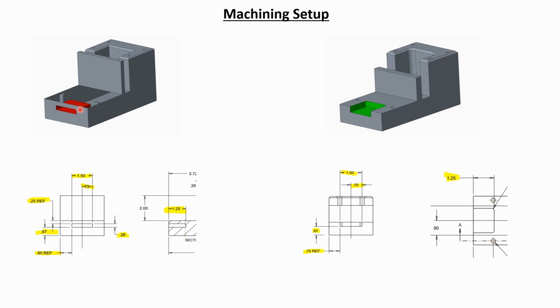The cutting tool approaches the workpiece at a 90-degree orientation. The original part will have to undergo a second setup to achieve that orientation. The corners of the internal features would also need to be rounded in order to use an end mill to achieve those features. If we look at the redesign, if the feature is redesigned as shown, then the entire part can be achieved within one setup, and unnecessary complexities which lead to more expenses can be avoided.